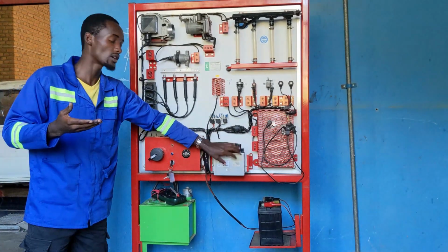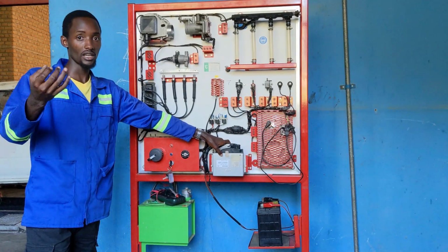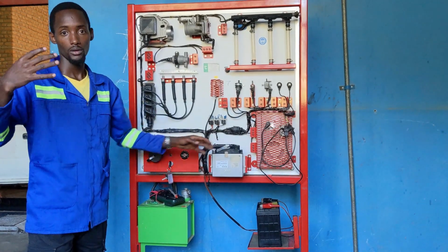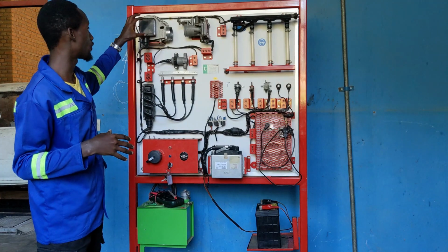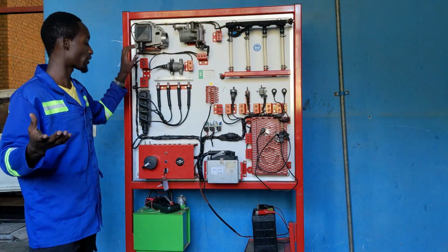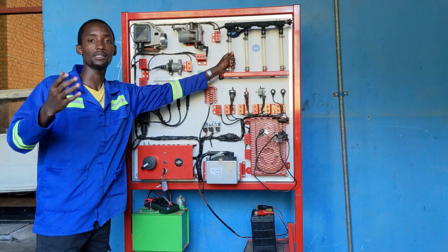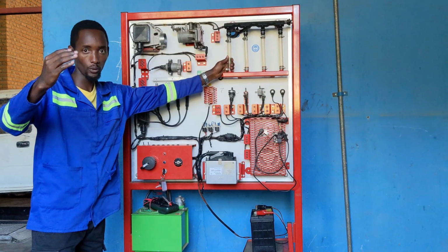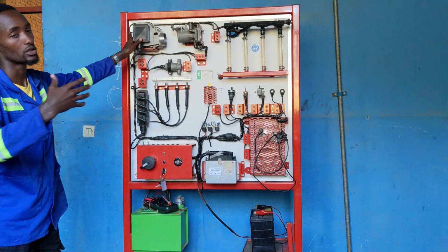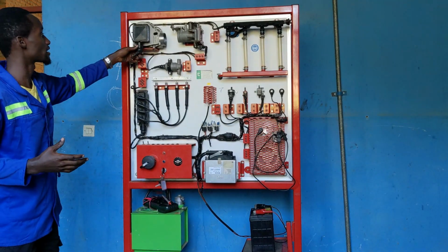So this ECU detects those physical conditions through the information the air mass flow sensor provides, and commands the injector to inject more fuel according to the air entering the cylinders. So there it is, the sensor.